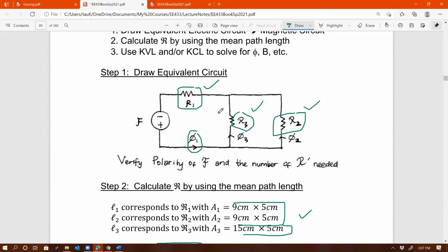If you know the value of all 3 resistances, and you know the voltage here, right? Let me erase that. So you know the voltage, you know the resistor values, but you don't know what the current is. Well, one way is to simplify the circuit by getting the equivalent resistance of all of these three resistances. How so?